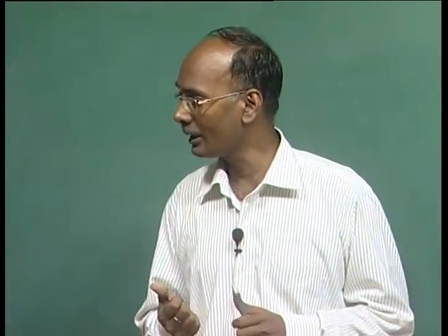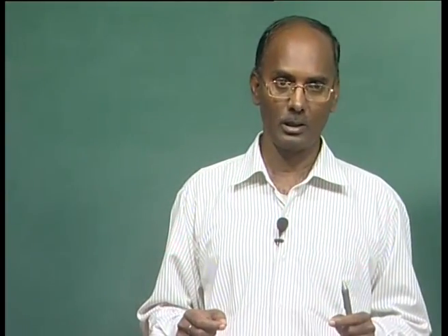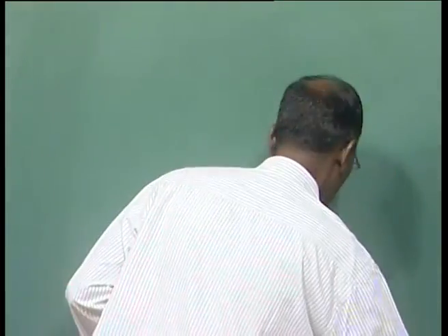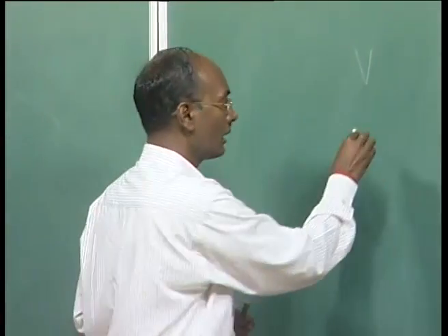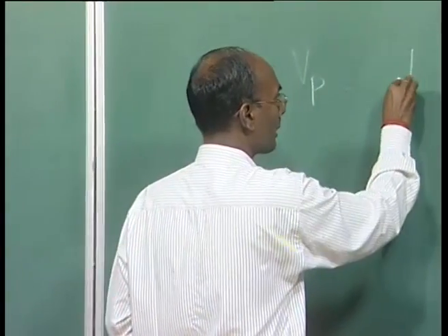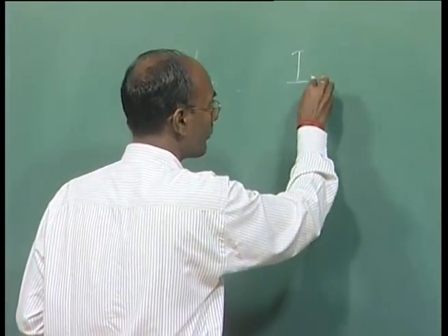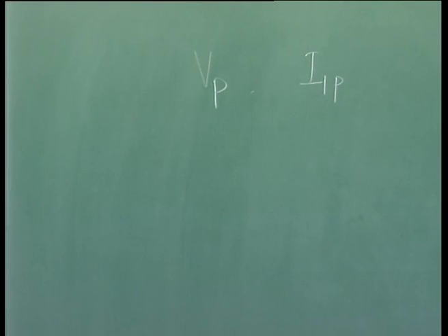The displacement factor is relevant if your loads are non-linear or you have some power electronics load. Then some harmonics also appear along with the fundamental. So the displacement factor is basically the angle between V, that is the source, in this case Vp, and then I1, the phase current. I1 is the fundamental component of the current which is flowing in that AC side.